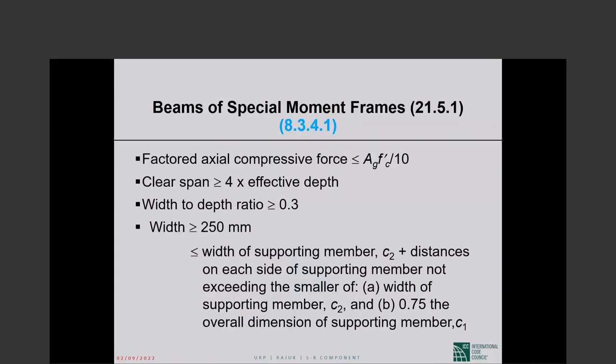The other way around, the depth of the beam has to be no more than 3.33 times the width. Okay, that doesn't give you a minimum. I do not know what to tell you. There is no minimum. If you want the beam not to stick down below the slab, you don't have a beam. You have a flat plate, and that I'm sure of.